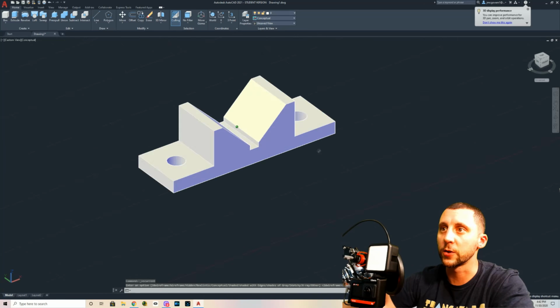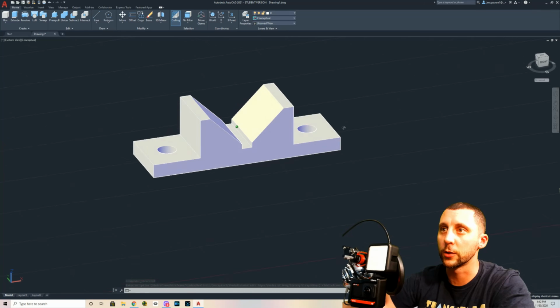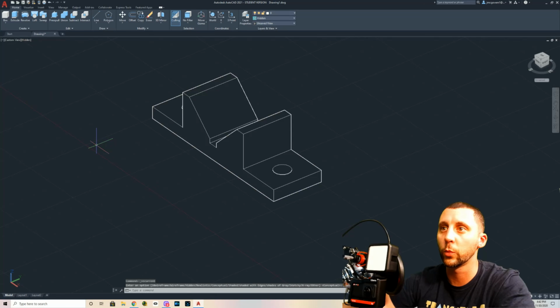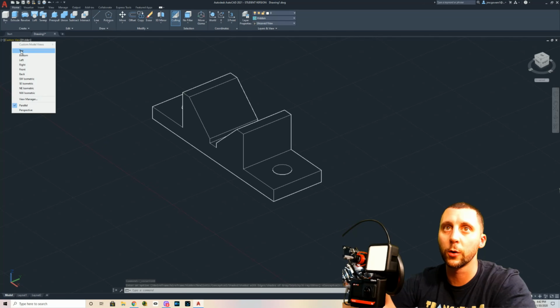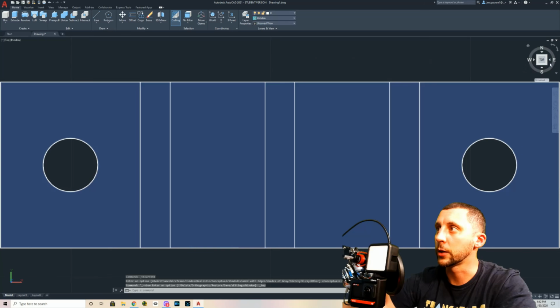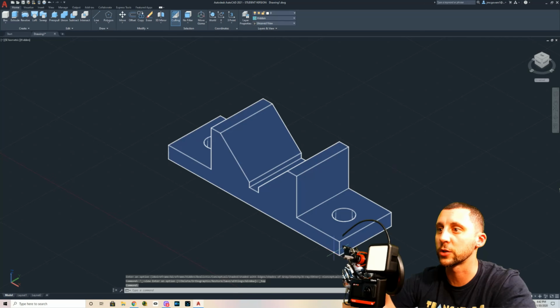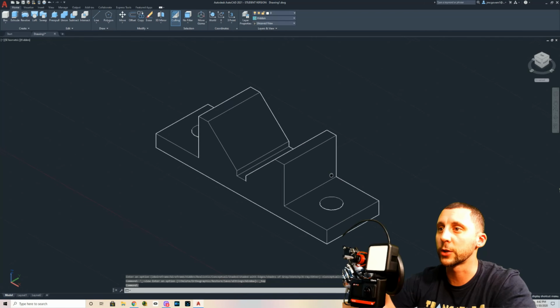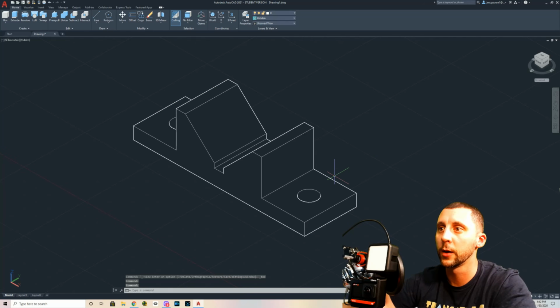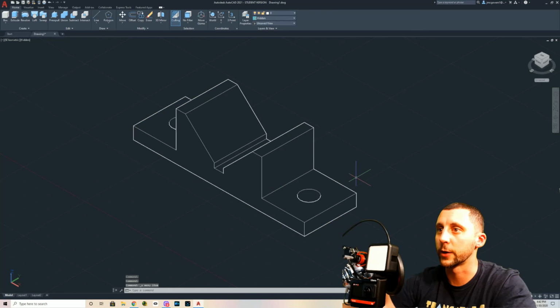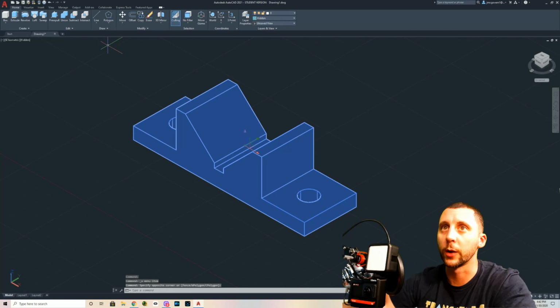Okay, now let's say you're spinning this thing around and you're looking at it and you like it and it's all good. What you'll do is you'll go to hidden when you go to print this if you're one of my students, but you have to reset your view. You've got to go back to top here, and you've got to go to the bottom right corner of the cube. That's a perfect 30 degree isometric setup. Okay, we don't want to print it like this. We want to print it perfectly isometric. All right, you can also put line weights on this by going back to your drafting and annotation tools.